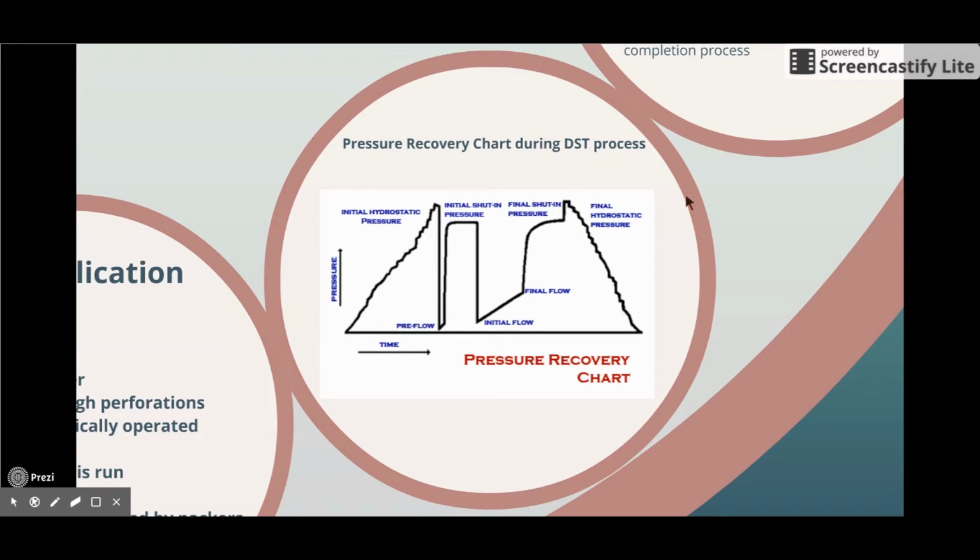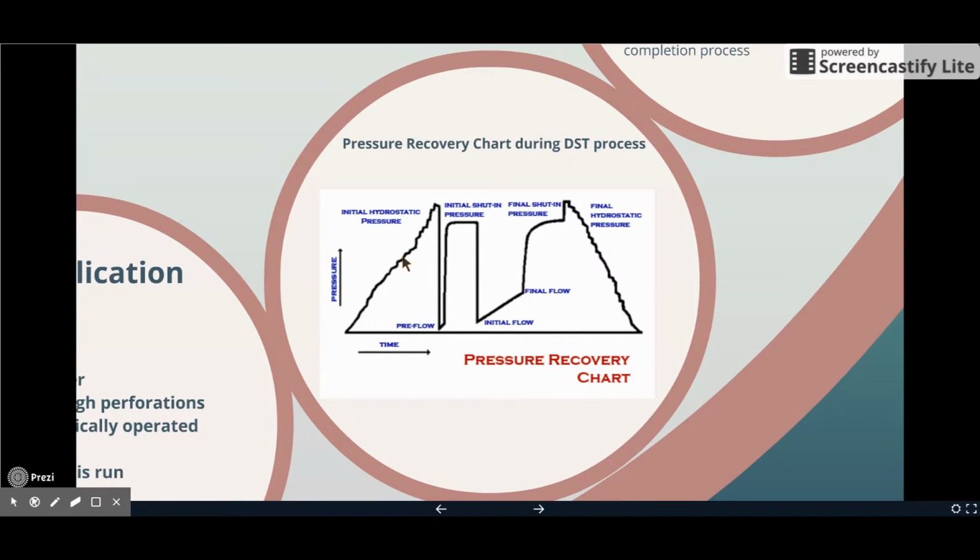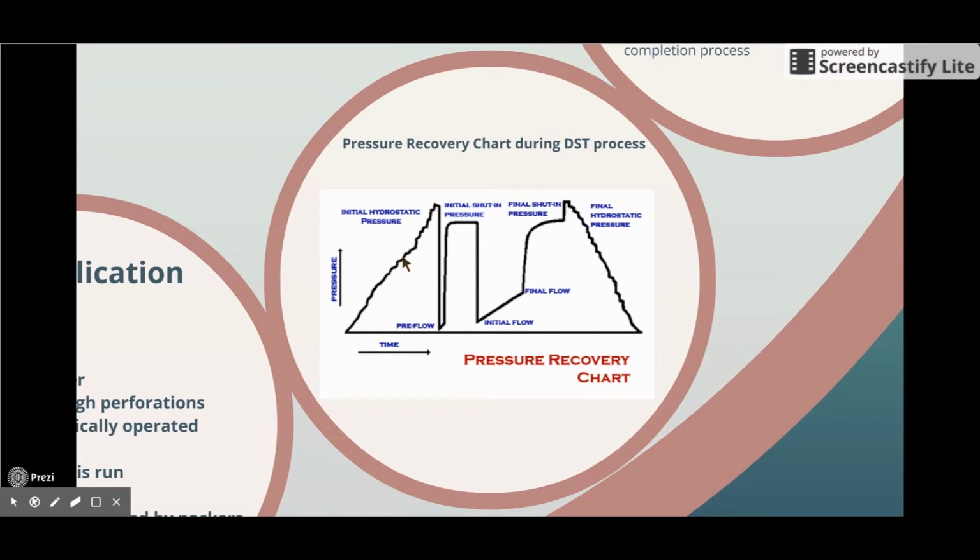The packer is not set yet. The pressure is due to the height of the total mud column. When the packer is set, the mud is compressed and the pressure increases slightly. This shows the sudden increase in the pressure in the graph.